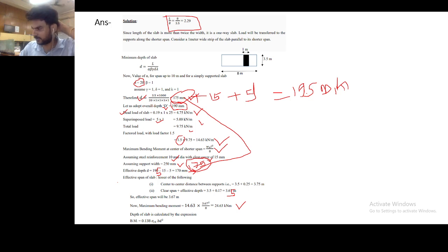It is a triangle, no? When we calculate the strain block and the stress block, we have not considered a parabolic stress block here, and in the strain also it is a straight line. So I think it comes from similarity of triangles, and we solve for the different depths. Whatever different strains are coming, it is proportional to the distance. I will draw here.